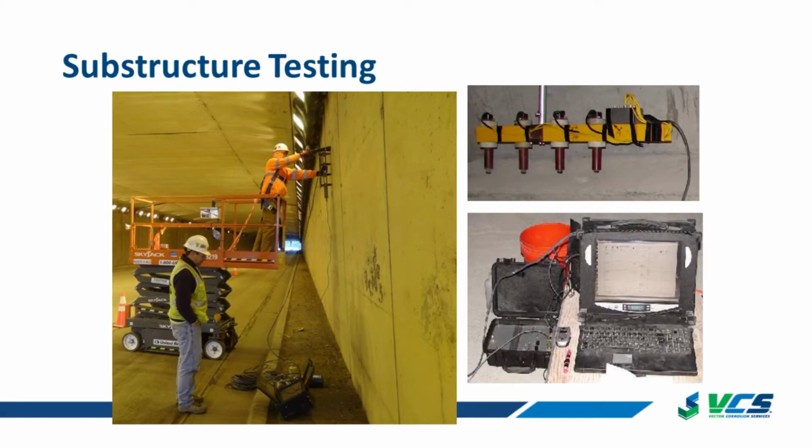And so with bridge decks, it's very common to be doing rolling impact echo. But also we can do it on substructure elements as well. We can have a handheld version of the sensor and an impactor and do it to identify those quantities on the substructure elements. And this happens to be a tunnel abutment wall. And so I'm just going to show a little bit of a piece of that area.